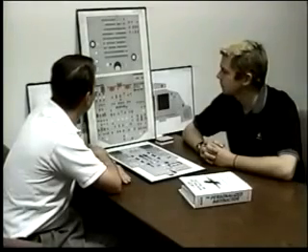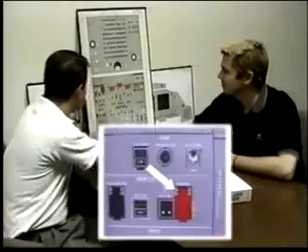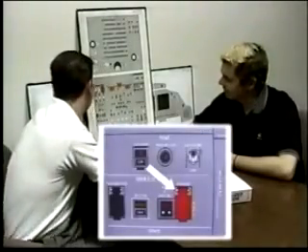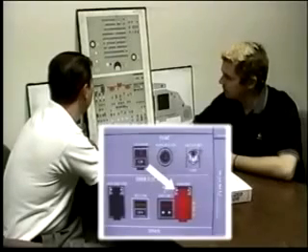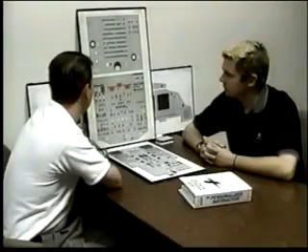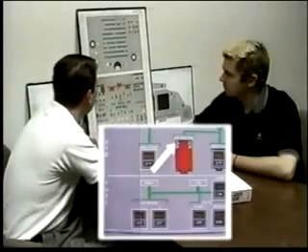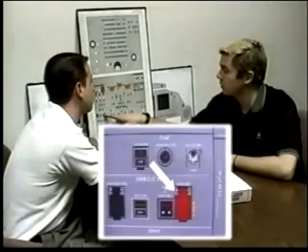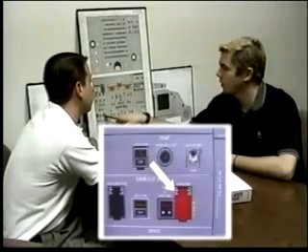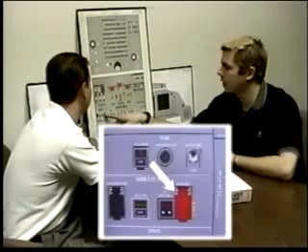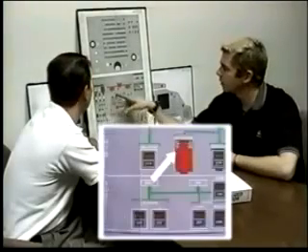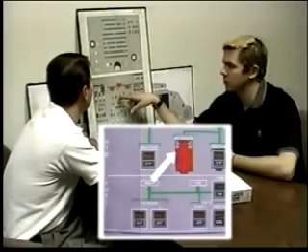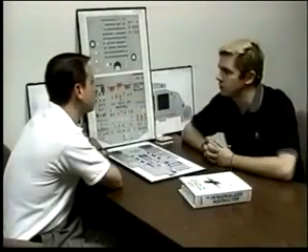Ram air turbine man on. You told me on the emergency electrical panel that selecting the RAT man on, I would get, if the RAT didn't deploy, the RAT should deploy, and I would get the emergency generator. Would I get the emergency generator with that RAT man on? No, this is just a manual on switch, and this is going to not only deploy the RAT, but it's going to open up a second valve that'll allow the emergency generator to be powered. Over here, we're only opening one valve when we do it, and it just allows the system to pressurize the blue system, but has nothing to do with the emergency generator.